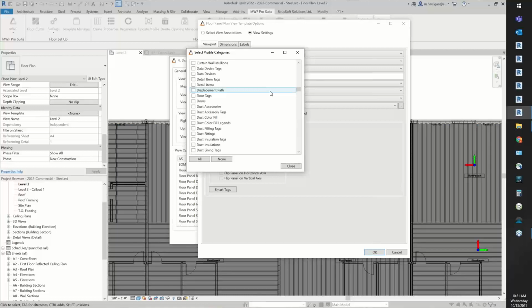However, let's say, for example, we would like to have our, I don't know, our floors shown. Let's say, for example, you can just have this option checked, and what's going to happen is when you use that drawing settings, your floors are going to show in your view because you had it checked in this option here. So you can say all, if you do want your Revit link, let's say, for example, if you just scroll down to the R's, you have your Revit links here.